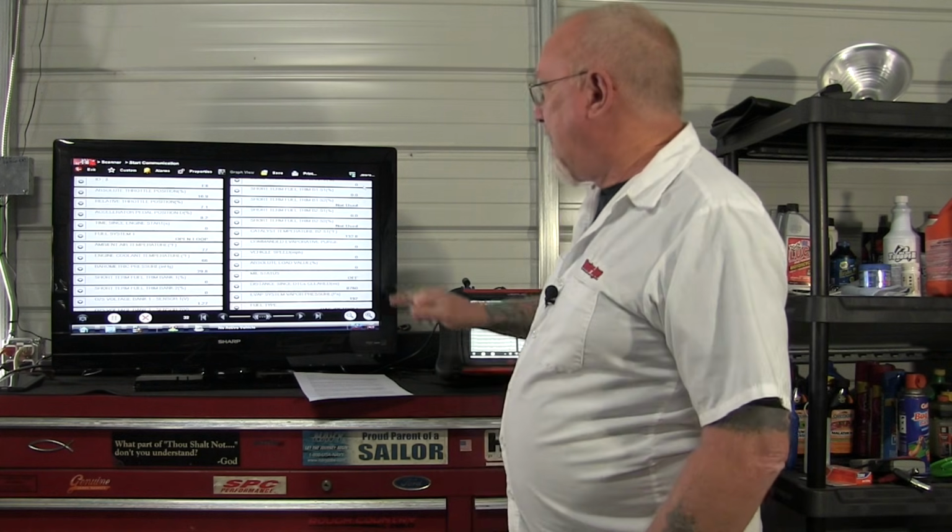For example, fuel trims are something I like to look at all the time. So I'm going to pick the fuel trims for sure. But am I really going to care much about MIL status? No, I don't need to take my time asking the computer if the MIL's on or not. I know it is, that's why it's in my shop. So pick the ones you want. That's going to help the refresh rates pick up, and will help you get some more current, accurate data, and maybe help you see something that falls out of whack if you're going to graph the data later on.